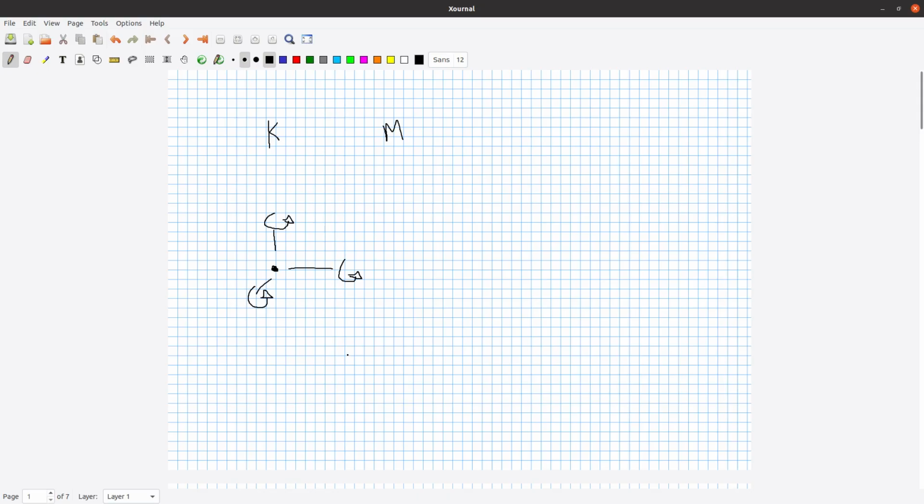Now, there is a problem when you define a node. When you introduce 6 degrees of freedom, there is a problem. So here, let's go ahead and write out a stiffness matrix here in the bottom. Whenever you create a new node, the stiffness values are all 0.